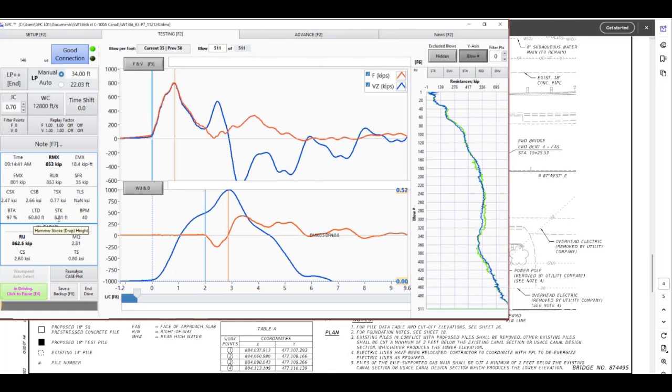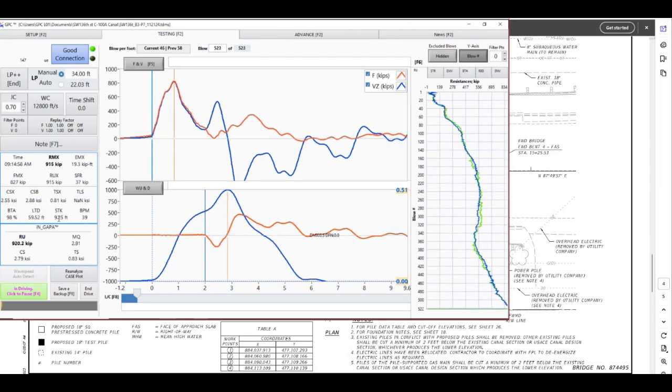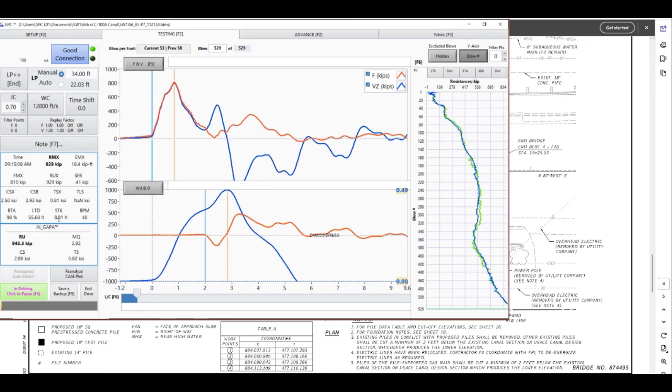Back to test pile and production pile designation. So a test pile in Florida needs to have a minimum of 10 feet in the bearing zone, which means a minimum of 10 feet exceeding the required capacity, and in general an increasing trend. So we do have it now.